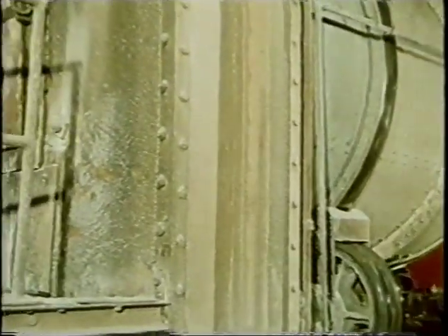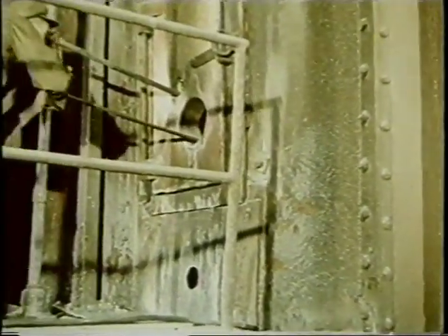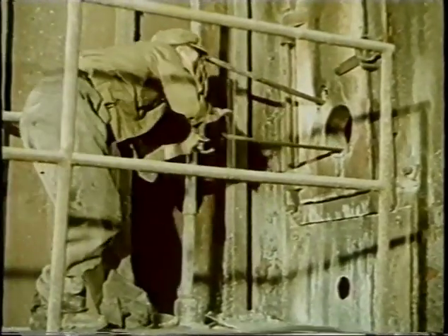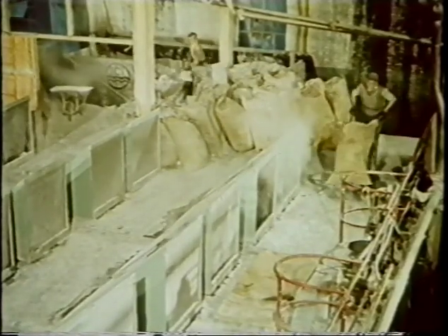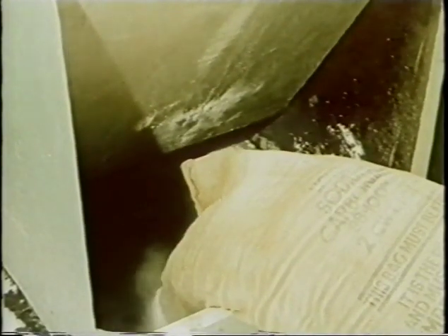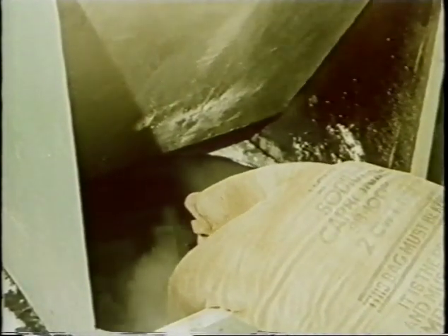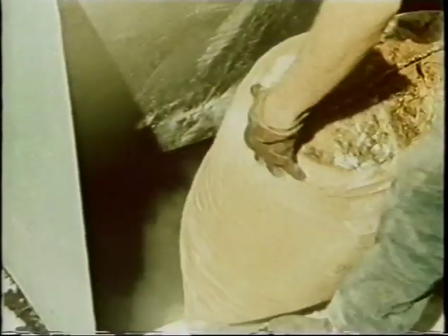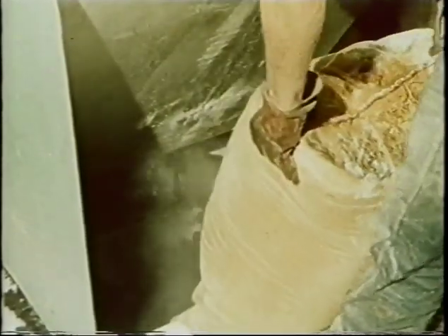In this, the organic constituents are burnt off, liberating carbon dioxide. The sodium compounds are converted to sodium carbonate. This, plus a small amount of unburnt carbon which settles out, is placed in causticizers of 10,000 gallon capacity. It is supplemented by 20% light soda ash, fresh from the factory.